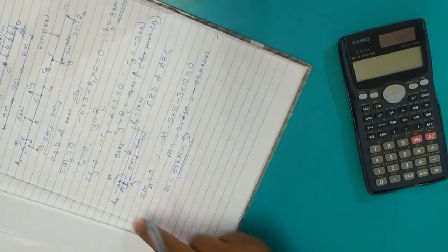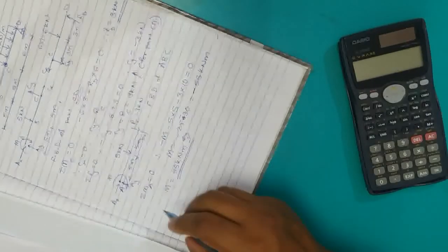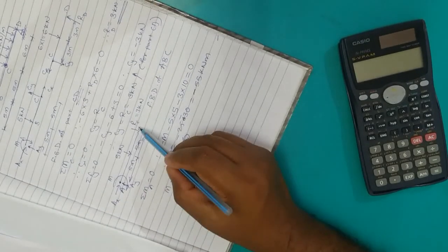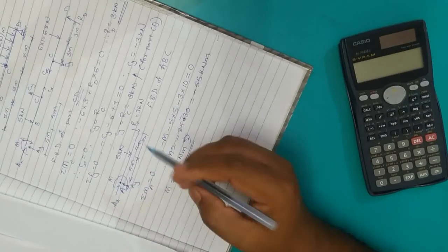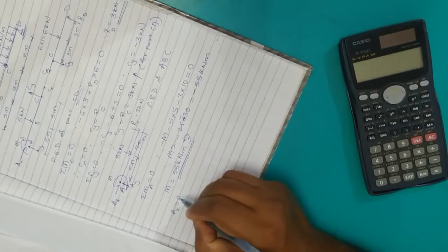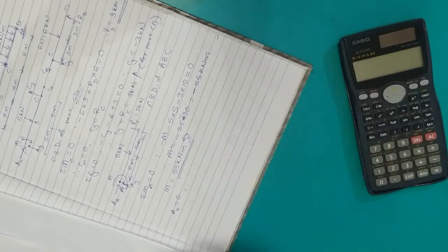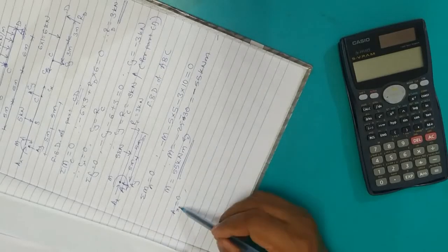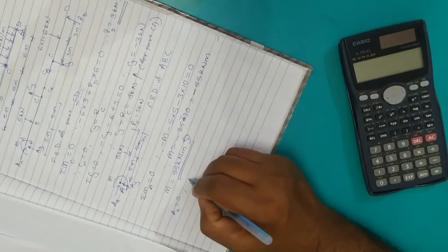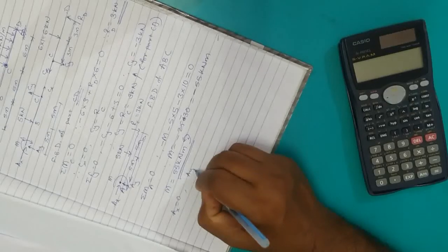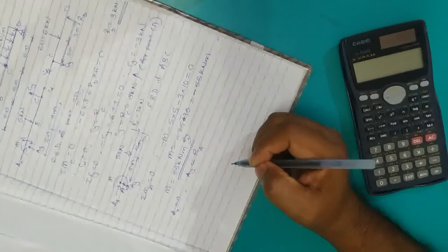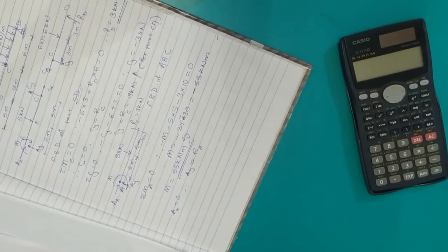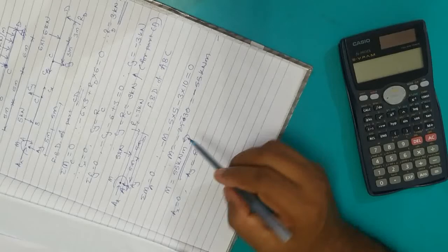Now the remaining two reactions, Ax and Ay. Again here we can say that Ax is the only horizontal component in the entire FBD, so Ax is going to be 0, or rather you can say summation Fx is 0, and then you can check all the forces, and you will get to know that Ax has to be 0 only. And because Ax is 0, we will say Ay itself is going to be the resultant reaction of the hinge, that is Ra. Sorry. And now let's try to find out this Ra.